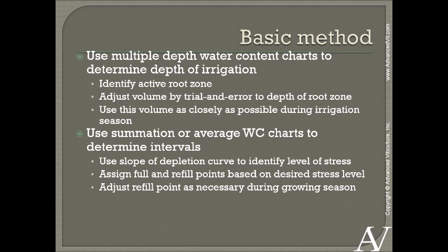But I look at the sum or the average of the water content down across the whole profile to determine how long it takes for that moisture that I just applied through irrigation to be depleted. And that really takes 100% of the guesswork out of this irrigation practice, in my mind. That really has saved me a lot of grief, maybe a lot of error, to do it this way. And again, a picture's worth 1,000 words, so let me just get to that. If there are any questions about what I mean by this, hopefully they'll be answered in the next couple of slides.